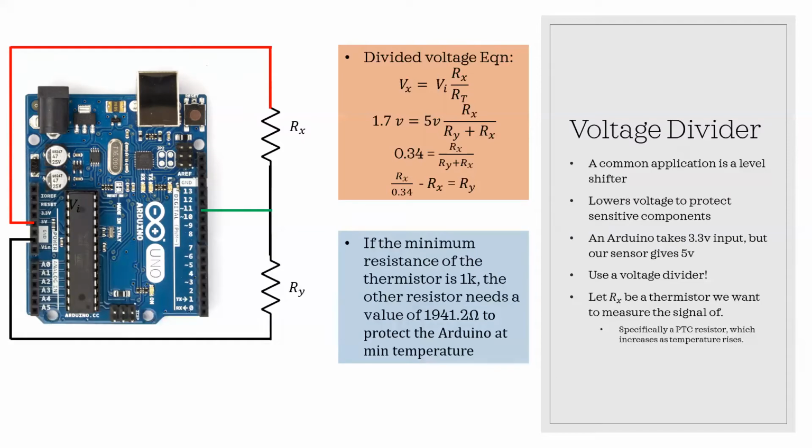For an example, let's look at something that's sensitive to temperature using a thermistor. A thermistor is a resistor that changes its resistance based on the temperature. Every resistor sort of does this, but a thermistor is really sensitive to a change in temperature and can change quite a bit based on even day-to-day changes in a room, like from 20 degrees Celsius to 21 degrees Celsius can see a very large change in the resistor value.